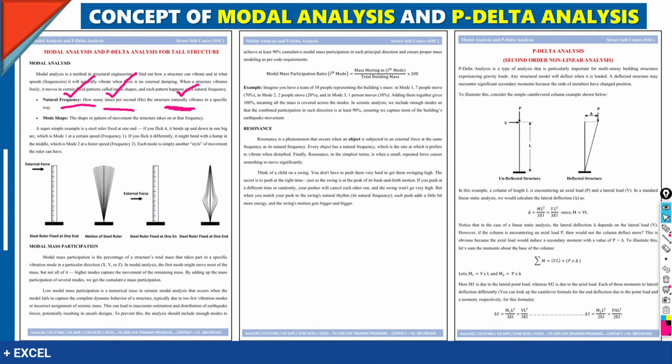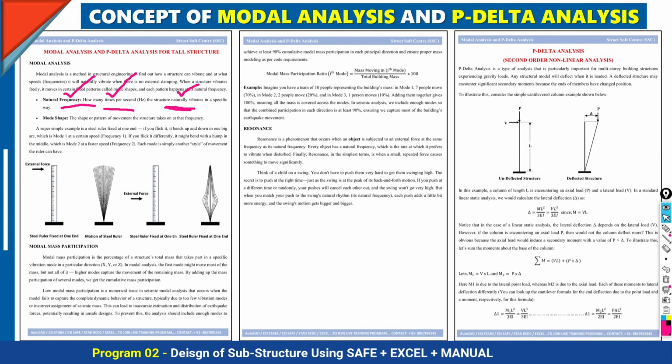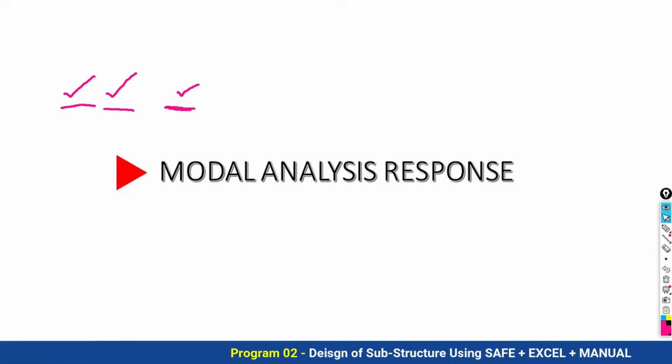What does modal analysis mean, why is it needed, why is it important? After performing modal analysis, you will be able to get the dynamic properties of your structure. Without knowing the dynamic properties, you cannot design the structure. So modal analysis is very important to get the mode shapes, the fundamental time period, and the frequencies. P-delta analysis, when to perform it, that we are going to see.